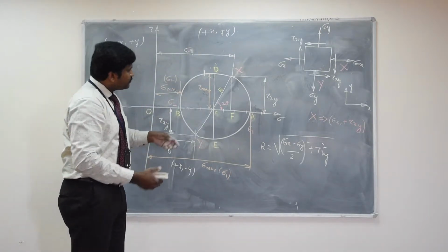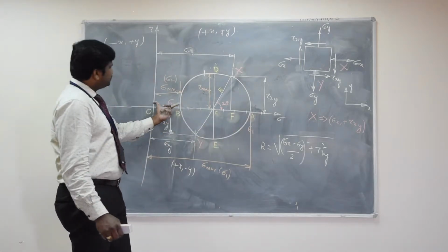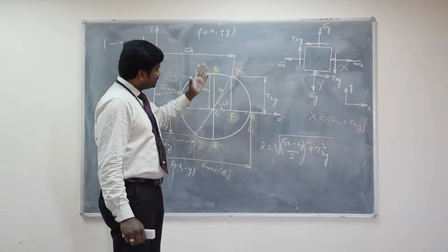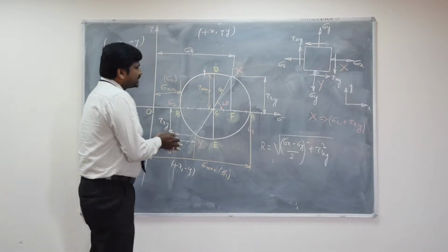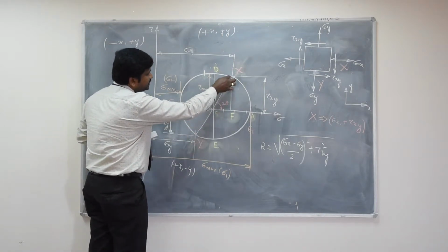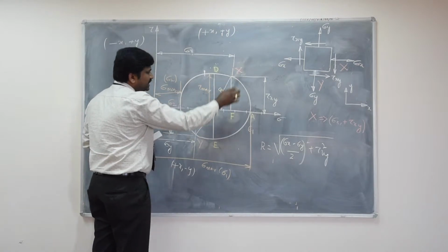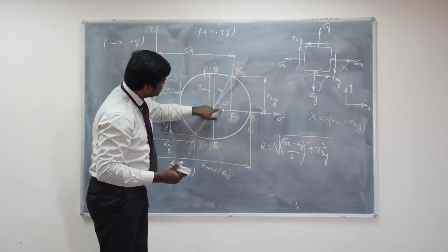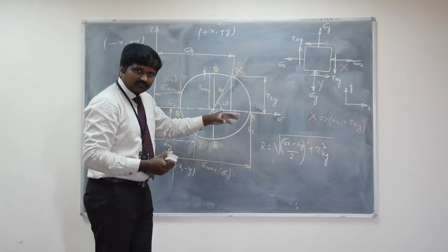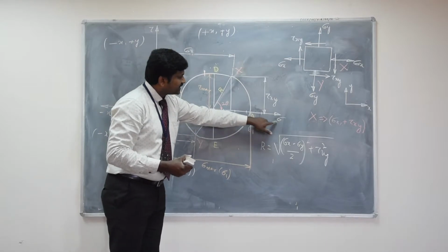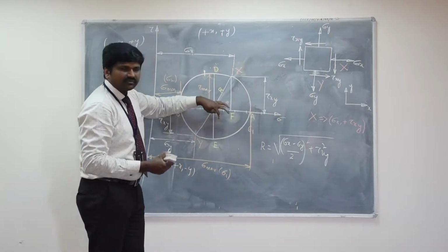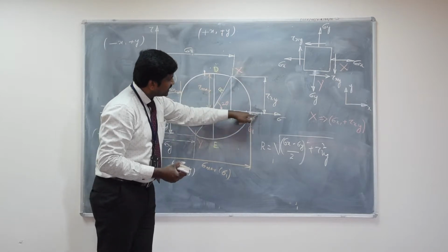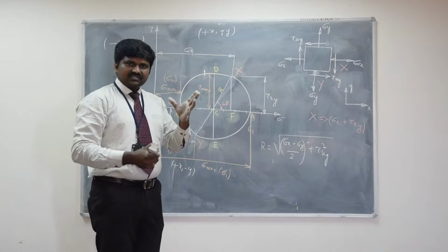So now from this Mohr circle diagram, we are able to measure the maximum principal stress, the minimum principal stress, and the maximum shear stress. Also, it is possible to measure the direction of the plane in which the stresses are maximum, that is the inclination of the plane. The inclination of the plane will be measured with respect to this xy plane. Usually with respect to point x and the sigma axis, the angle will be measured. So this is the angle, from this plane to the sigma axis. This is 2 theta. The direction is the direction in which, if you rotate the plane x, it will merge with the sigma axis. Here I have written the direction, that is the clockwise direction. If you rotate this plane x in the clockwise direction, it will merge with the sigma axis. That is the direction for the plane where your stresses will be maximum.